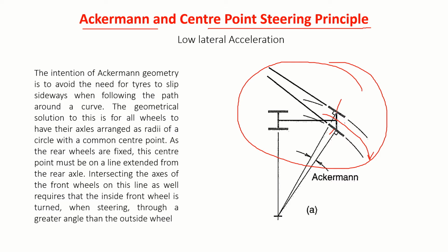Similarly, for this wheel also, I draw a perpendicular at the midpoint. The rear wheels also I draw. All these lines will meet at one point.